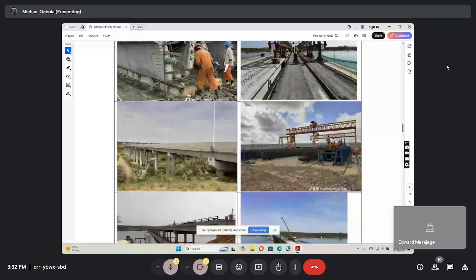Repair, rehabilitation, addressing structural damage. So arising from inspection, you are able to attend. Then you can see whether you do minor repair, major repair, or rehabilitation. So you are going to sit down. We did rehabilitation of Karuma. We checked, we inspected, but then we realized the cracks were too much. So it was required that we remove the deck and replace. So these are all new reinforcement.